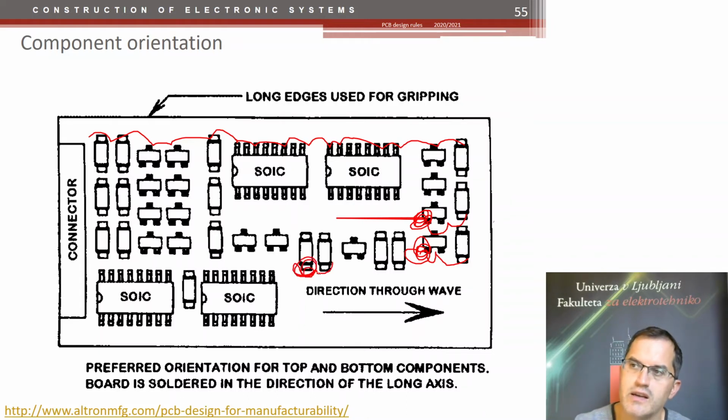And here you may get a problem with the solder shorts. Okay, the last pins here are always the problem. You will always have issues with these, because the big solder bumps at the end are always present. I will show you how to get rid of it.